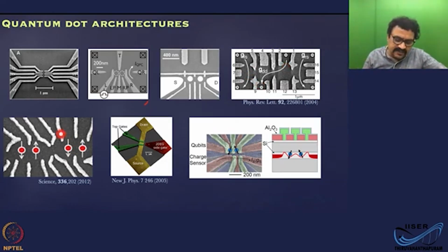And this is slightly a different variation again. If you look at it, instead of 2 dots, there are 4 dots actually. If you can energize all these, you will get 4 dots, not 2. Okay. Now, when we come to here, this is actually a silicon quantum dot. Now silicon germanium quantum dot. All these that we have discussed are gallium arsenide, aluminum gallium arsenide quantum dots. There are various ones there. If you look at the literature, you will see a lot of variations of these designs.